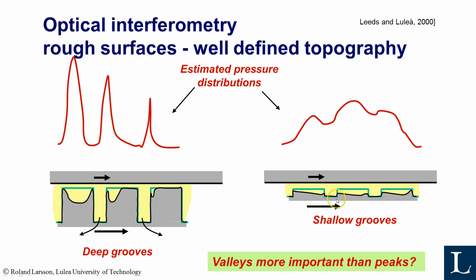While if you have more shallow grooves, this will not happen as easily, because then you will have some flow resistance in the grooves and pressure is formed also in the groove area. So that means that you should also be careful with how deep the valleys are in the surface roughness. Maybe valleys are more important than the peaks themselves.